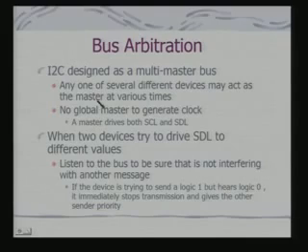Any one of several different devices on the bus may act as the master at various times. And what you have observed, I think by now, is that there is no global master to generate a clock. In fact, the device which is currently driving the bus becomes the bus master, and the master drives both SCL and SDA as the case may be.